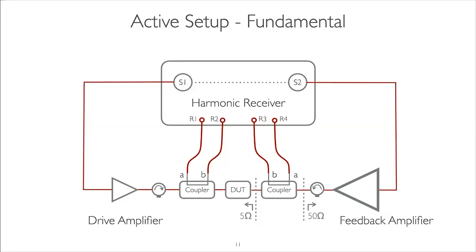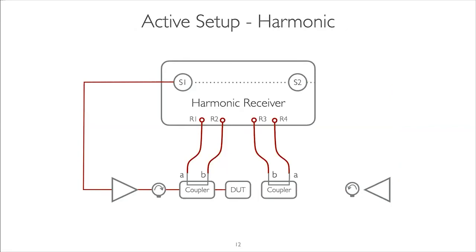But amplifiers can be broadband, but again, as you increase the power, they become less narrow band basically, and the components that we put in front of them, like these isolators, are basically there to protect the amplifiers, because as we're sending the signals back to the devices, signals are getting reflected back, so we need to terminate that signal back into the load. So those are narrow band components, and we'll see there's more components as we increase the capability. So if you're going to go from one frequency to another, these are components that you need to look into and swap when you go from one band of frequency to another.